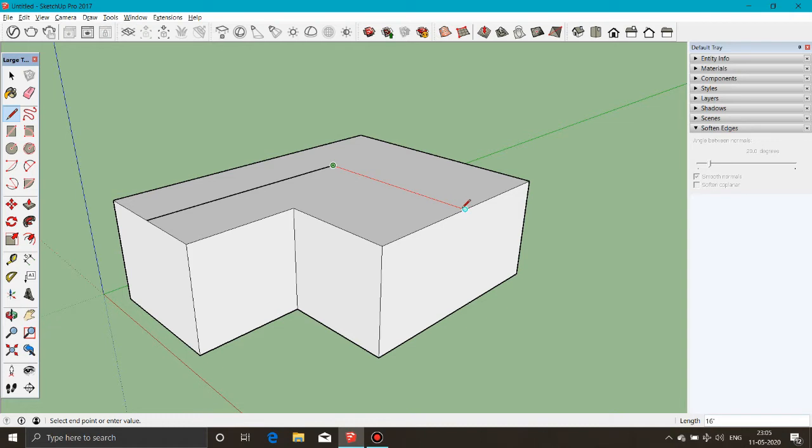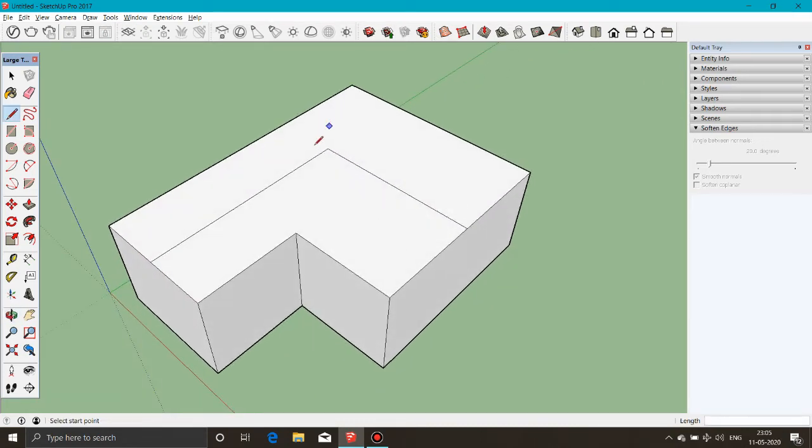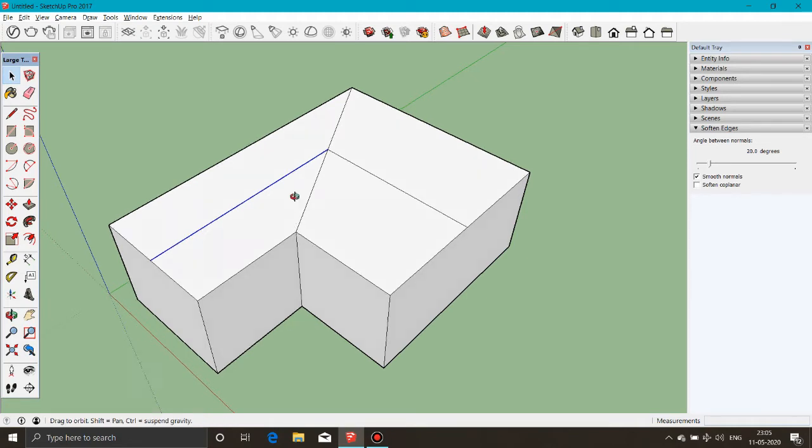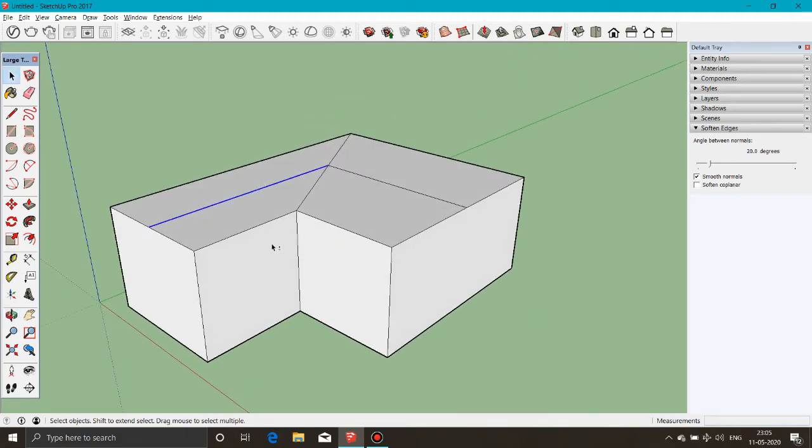Now that we have both ridges in place, simply draw the line where the roof will fold when we move the ridge lines. Use the Select arrow and click on one of the ridges. Then, hold the Shift key and watch the icon. There is now a plus/minus that indicates that you can add to, or subtract from, your current selection.